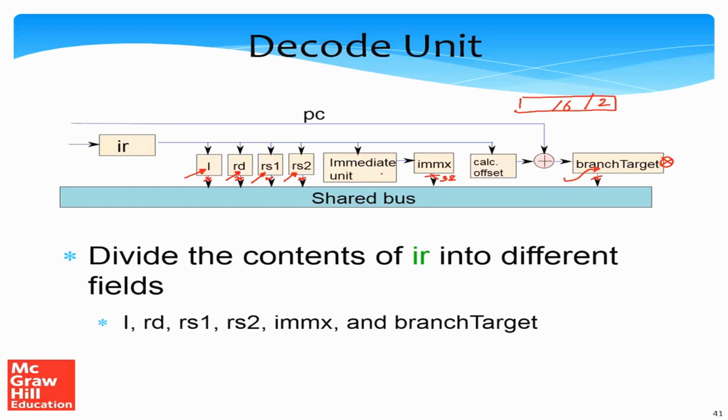So to read these registers, or rather micro registers, what we need to do is we need to send a command, for example, to read IMEX, and then this connection from IMEX to the bus will get enabled, and what we'll see on the bus is the value of IMEX which others can read. After reading, again we'll send one more command, or automatically this link will get cut off and the bus will not contain the value of IMEX. So what again is a shared bus? It is a set of shared copper wires. Alright.